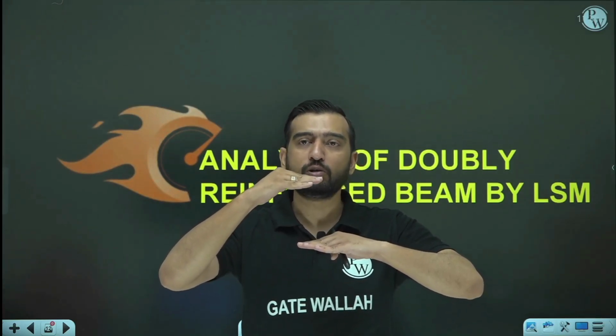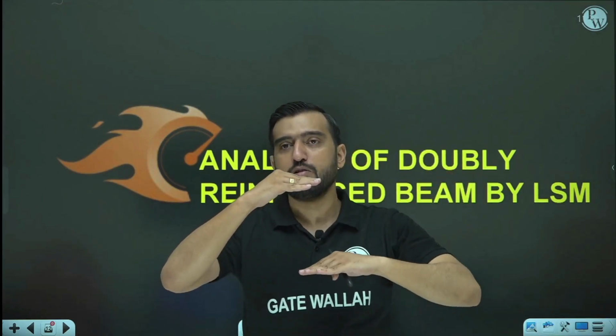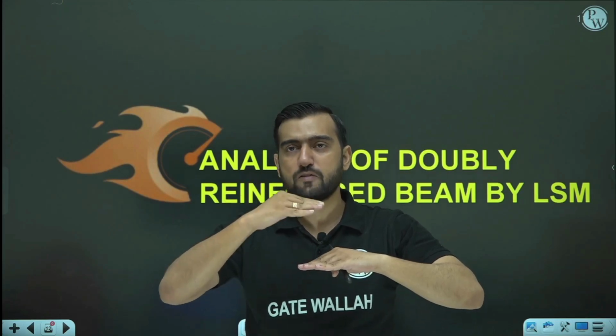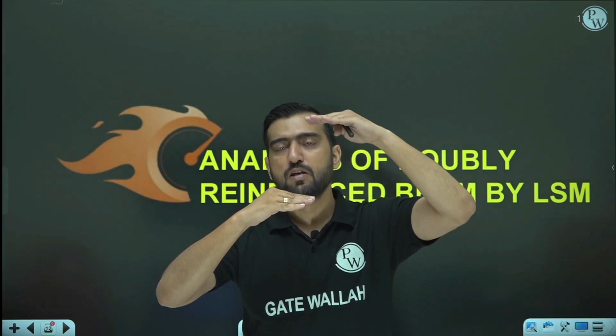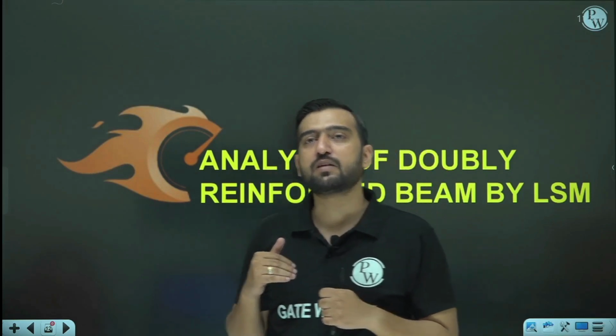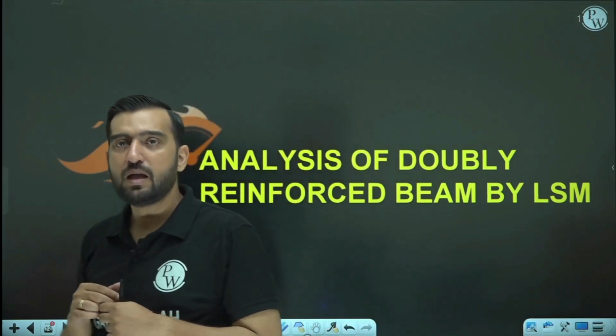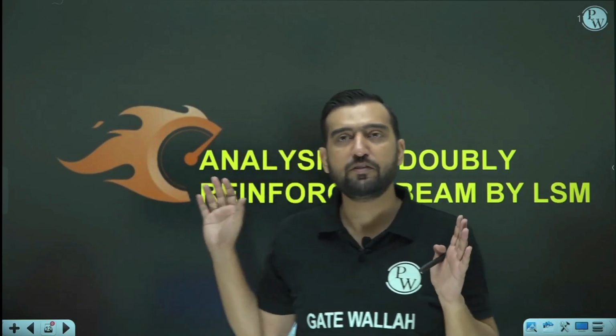do, you need to increase the density of the upper area, or you need to add more load on the upper side. So you have to compensate this difference by inserting some amount of bars in the compression zone, so that my neutral axis can again come back to its original position, again come back to its XU lim position, because till XU lim things are entirely effective.